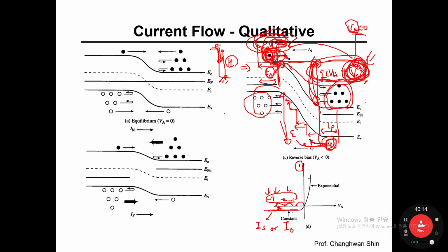Okay, so in figure D, you can clearly see the measured current versus voltage characteristic of PN diode. Here in the forward bias, the current is exponentially increasing as forward bias is linearly increasing. But when the reverse bias is increased at a linear pace, whatever the magnitude of reverse bias is, always a constant amount of current is flowing. In other words, saturation current is flowing. So this IV characteristic comes from the ideal PN junction diode. Again, ideal PN junction diode.